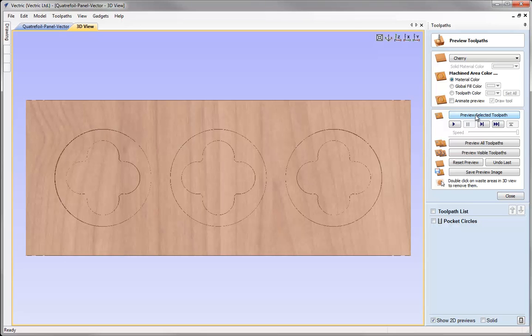Another thing that we can do is we can also apply a toolpath colour for this, just to make it a bit easier on the eye to see what has been machined away. So you just select this option here to select a toolpath colour, and from the drop down we can select any colour. That just helps us to visualise what has been machined away from the material block a little easier. But we can also use this function to help paint the preview picture if we were going to save, say, a preview image to send to our customer for approval.